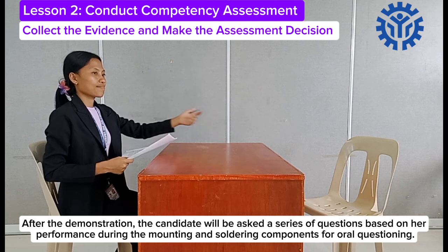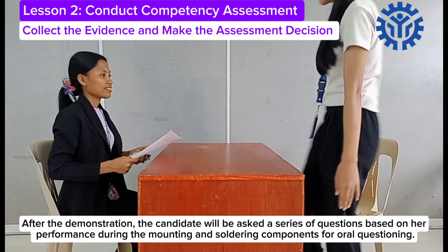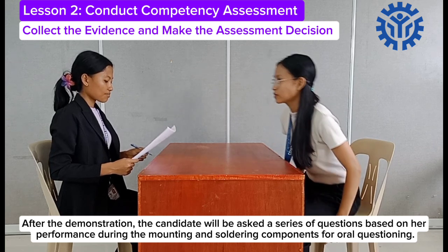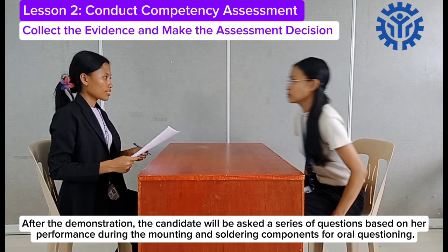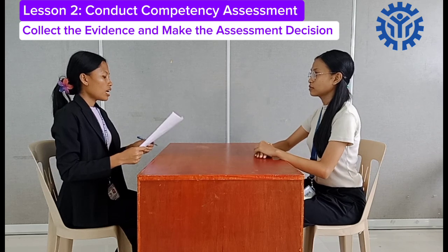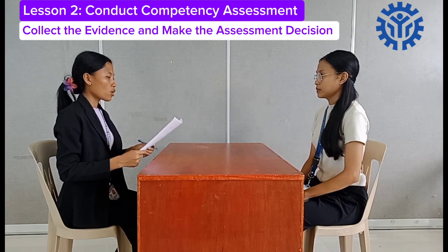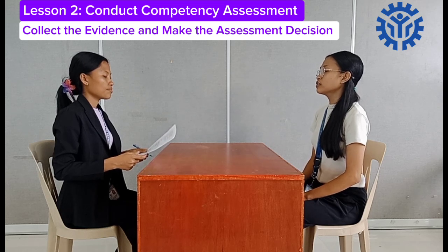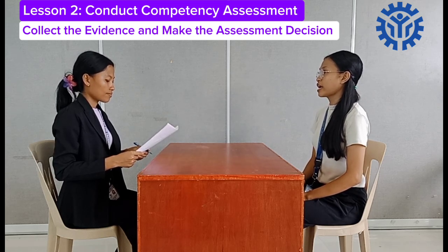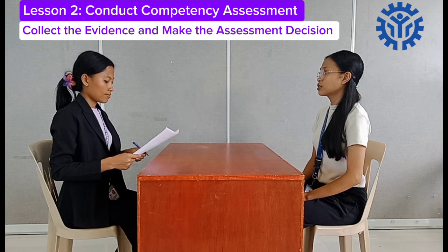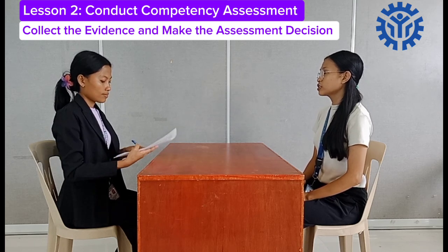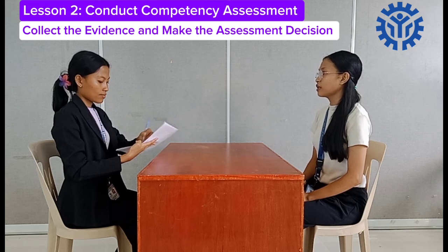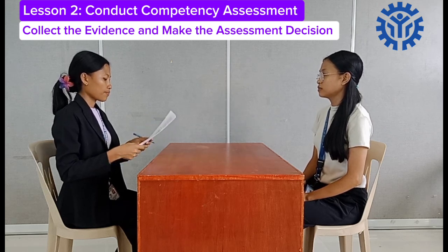After the demonstration, the candidate will be asked a series of questions based on her performance during mounting and soldering components for the oral questioning. How are you going to identify faults in electronic products? I would use tools like multimeters and oscilloscope to check for electrical issues such as wrong voltage or broken connection. Visual inspection and testing individual components help identify faulty parts.